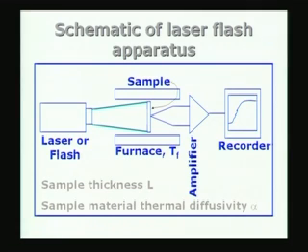So the laser flash apparatus is going to give me only the thermal diffusivity, and if I know the other thermal properties like the specific heat, which of course I am going to discuss a little later, and the density, I can estimate the thermal conductivity. So the method is very simple in terms of its application.